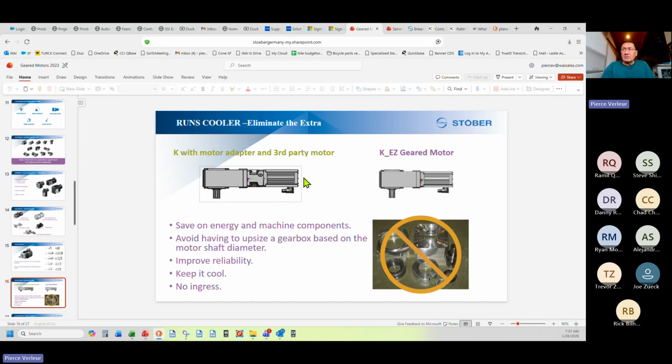But for the most part, you're relatively standard. You have a pretty good chance of being able to replace this motor with another motor should the motor fail versus the gearbox, and vice versa. You have a coupling in here, which makes it easier than this. Here you're locked to the OEM. So there's advantages and disadvantages to both.